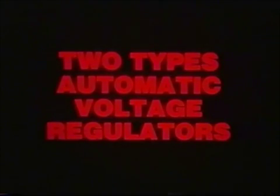There are two basic functional types of automatic voltage regulators. The first, and most common, senses only the output voltage of its alternator. By varying its output, this regulator maintains or attempts to maintain the alternator's terminal voltage at some preset level or value, regardless of any variation in the alternator rotative speed or frequency.